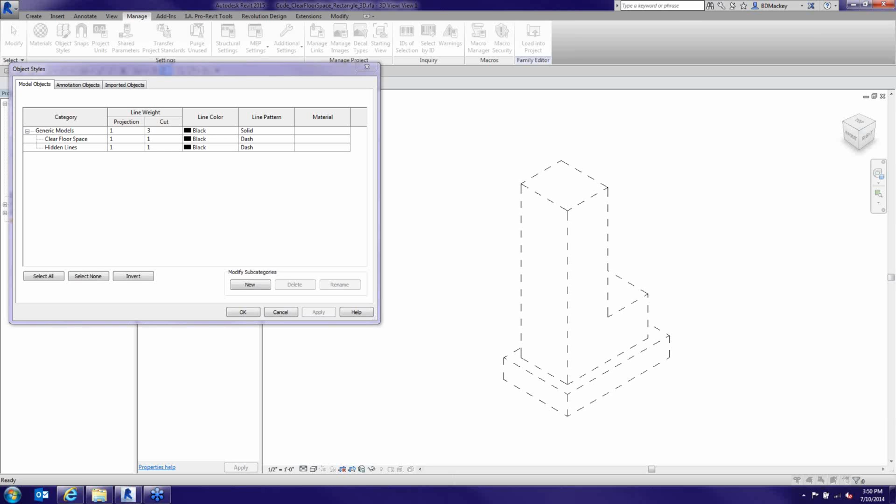So unfortunately with pipes, I don't know of a way. There could be a way out there and it could be incorrect. But what you can do is on connectors. So I usually just put a connector at the walls, and then I use the cuts with voids tool to cut it out through the wall, and I can go through and bust out all the openings in the wall. Again, that's only if you're in the same discipline. If, like most practices, mechanical, electrical, and plumbing is in a separate model than the architect, then that theory doesn't work for cutting, but it would still work for having those in the connectors. And then if you're in Navisworks, you can do a hard or a soft collision, and you can add some room for insulation or various factors like that. But you do have to be in Navisworks.